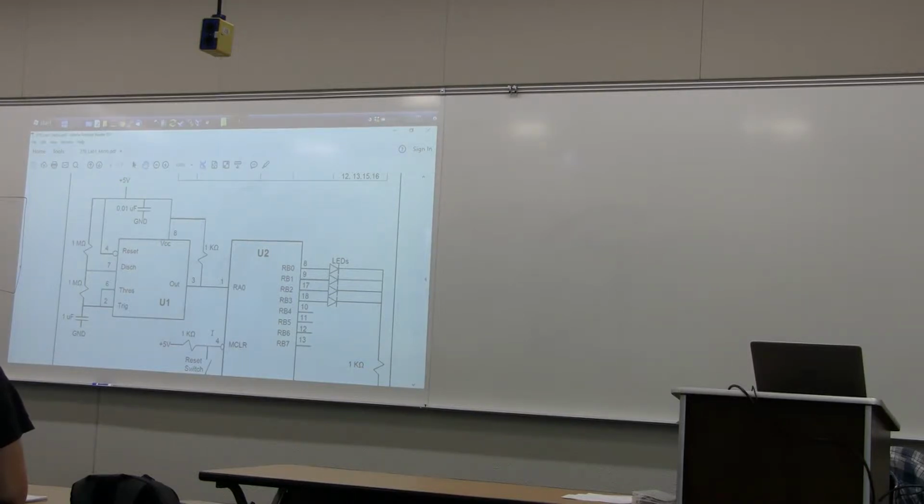First thing I'm going to do is take my power supply, and power supplies have 3 things on the bottom: negative, ground, and plus. We want to ignore ground, even though we always use the word ground. That's not what this is. This is actually called case ground. It's electrically connected to the outside of the power supply. What we really want is the negative output and the positive output.